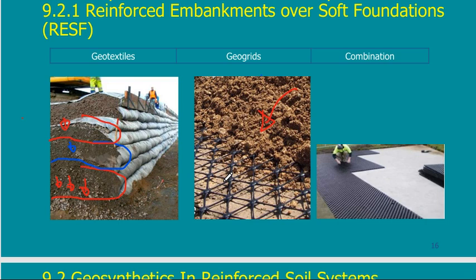So I'm afraid using this grid will not prevent water from carrying the fine particles. But using the geotextile, because it is like a cloth, it just lets water pass, keeping the particles in place. So this is a benefit of geotextile.